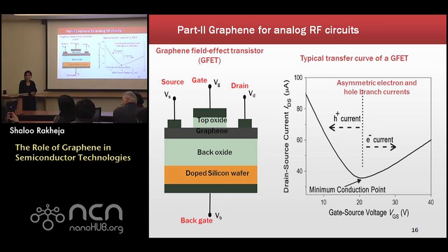And then one simple question on this pie chart you showed near the beginning. You had about 50% of the power dissipation due to the interconnects. About 25% was due to gates. That must be the charging, discharging, and the rest diffusion. Parasitics. It's parasitics. When Intel people did this, they called it diffusion, so I didn't want to change it. And I think they're talking about parasitics because for advanced technology nodes, the parasitics are almost equally high as your actual gate capacitance. They're becoming very, very important. So I think that is what they're talking about. But that is all related to the gates.